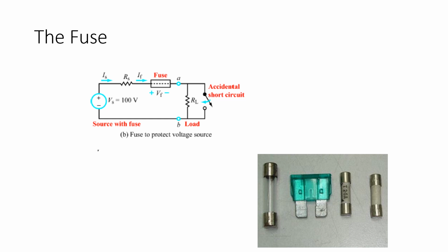It's all going to go through that short circuit down to the fuse. And so that, back to the source, not fuse, excuse me. So all of that current is going from the VS through the RS, which is inside of the battery, and then it's all going to the fuse and then directly down to ground. So this fuse is going to get really, really hot real fast.